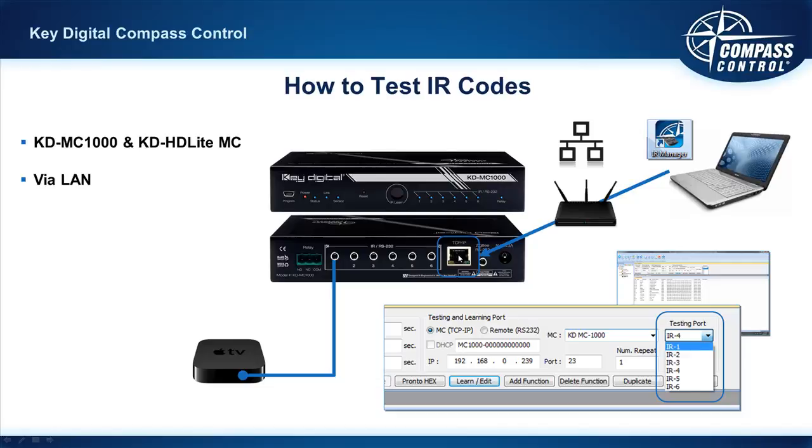And in order to test commands, there is a property or a setting we'll choose in our window where we could choose any of the multifunction ports on the MC1000. You'll want to choose the port that corresponds with the connection that your IR emitter is connected to.